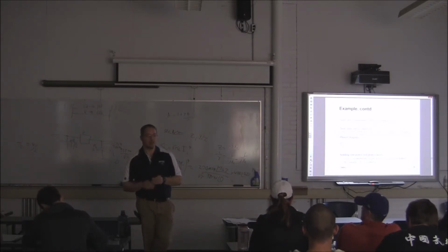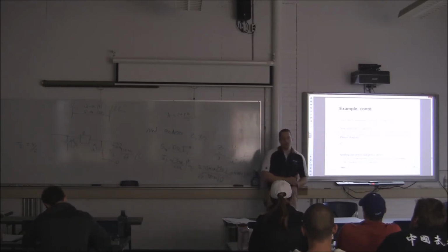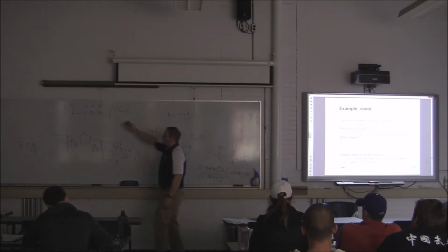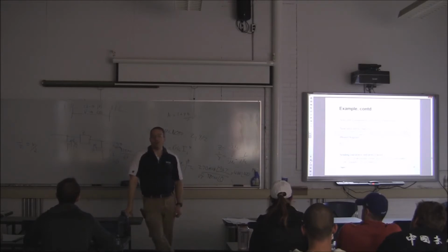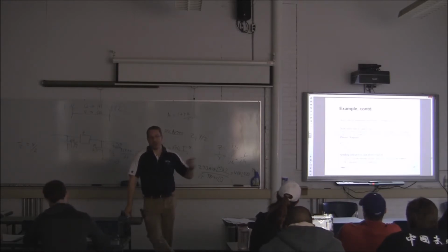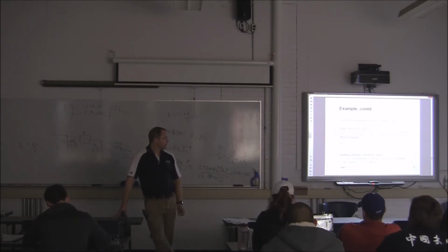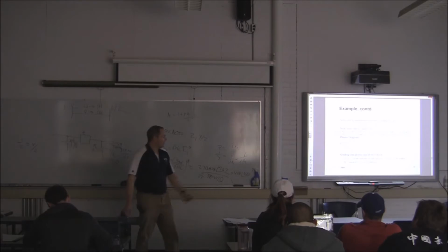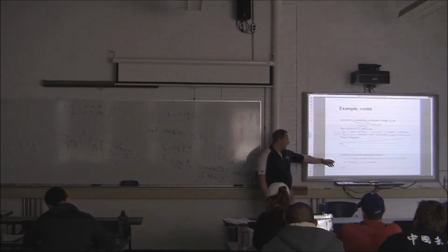Remember we talked in this class a little bit about phase shifting transformers? Same idea. A phase shifting transformer will introduce different phase shifts between this end and this end, and its whole purpose in life is to reduce power flow in that transmission line. So that's why they use phase shifting transformers. It's just to change the angle so you can either increase or decrease the amount of power flow from bus 1 to bus 2, for example. Okay? You can check that out if you'd like. Then the last thing is input power and power factor.